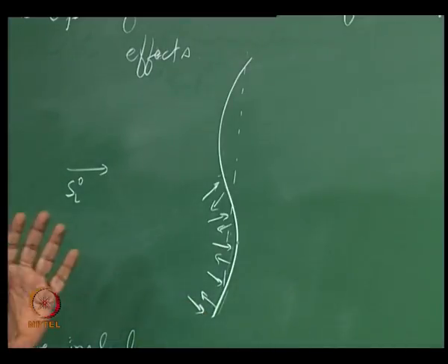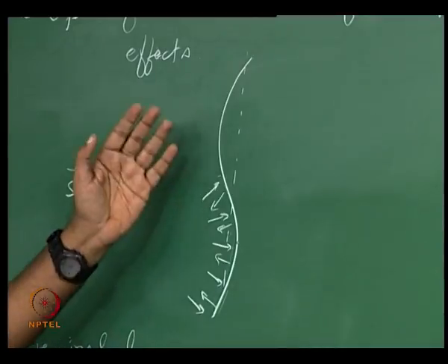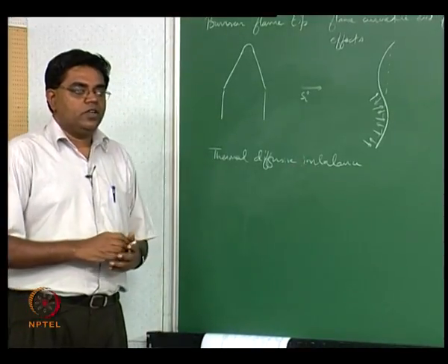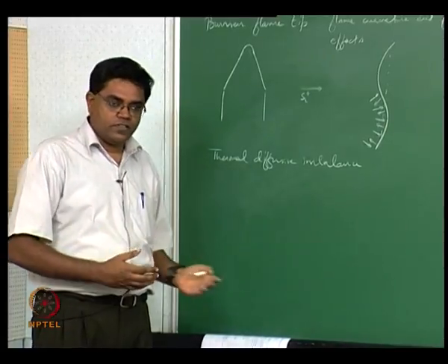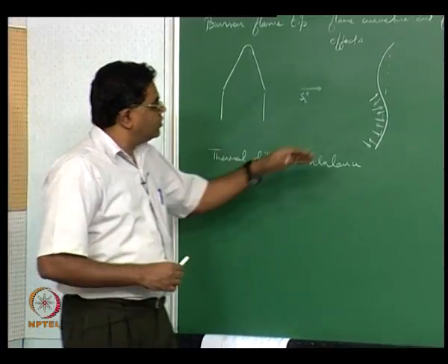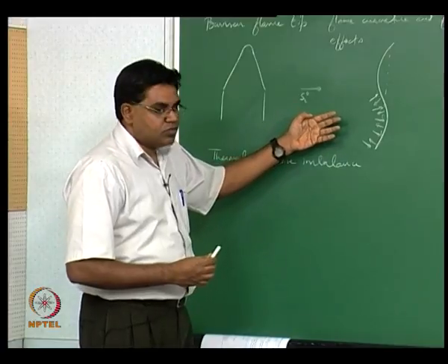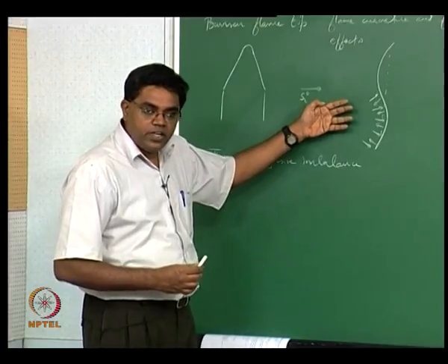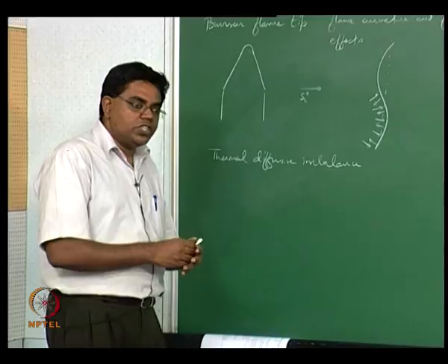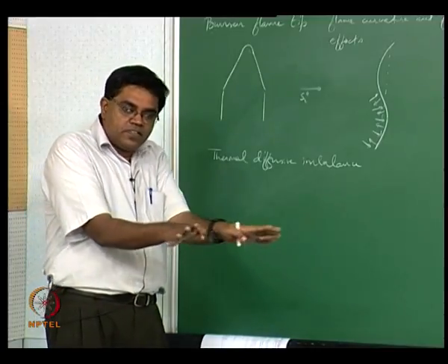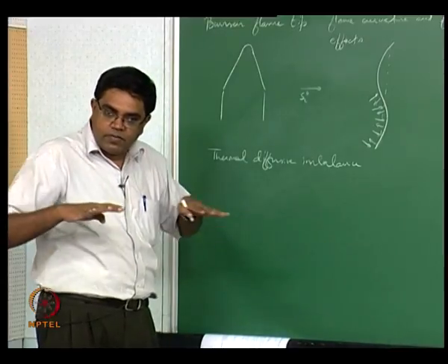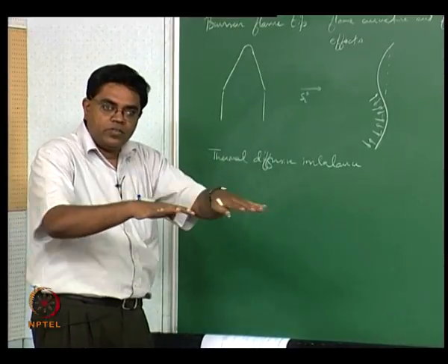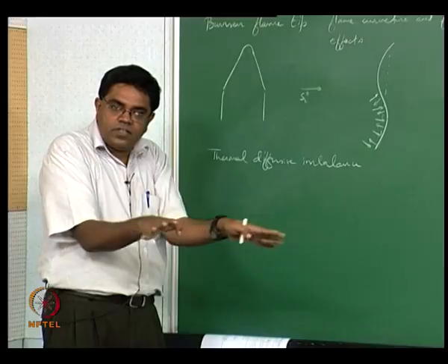Typically when you are looking at something like a fuel lean flame, the diffusion reactant is fuel, so it is more critical to think about the diffusion reactant. The diffusion reactant now spreads thinner in a radially outward manner. So instead of feeding a planar flame straight, it is spreading itself thin.